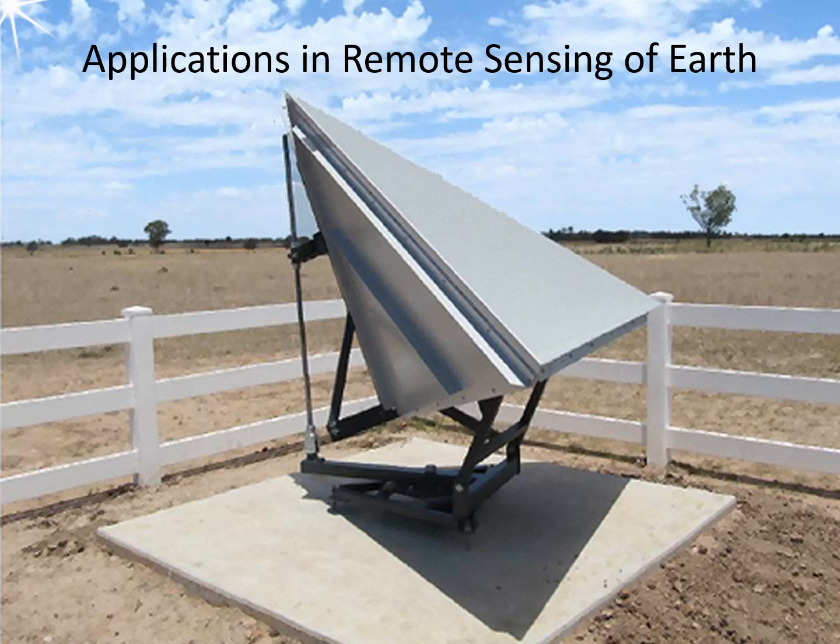They are used to acquire displacement measurements over areas that are densely vegetated or covered by snow, monitor specific locations within your area of interest, and calibrate the radar receivers in satellite radar. The edge length A is equal to 1.5 meters. This corner reflector has a radar cross-section of 75 square meters at a frequency of 1 GHz.